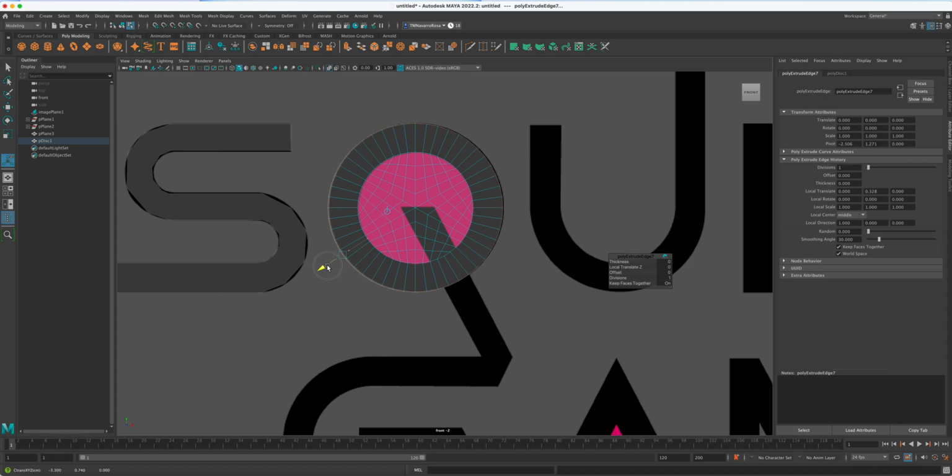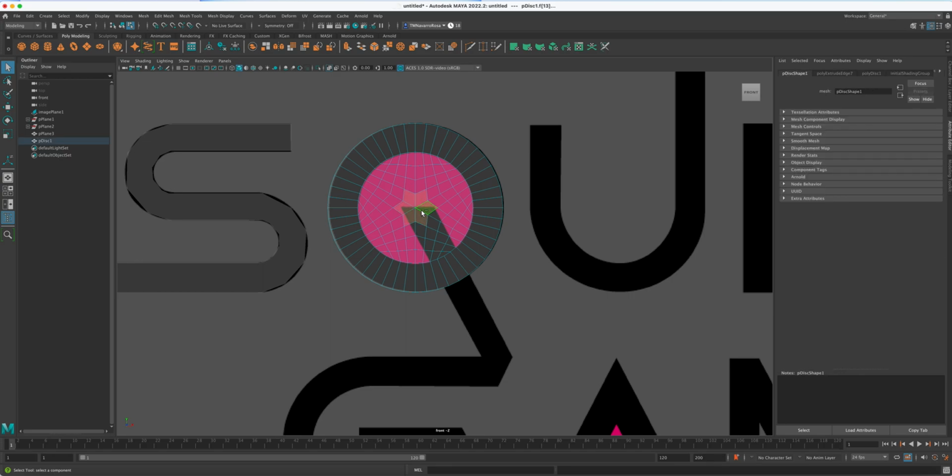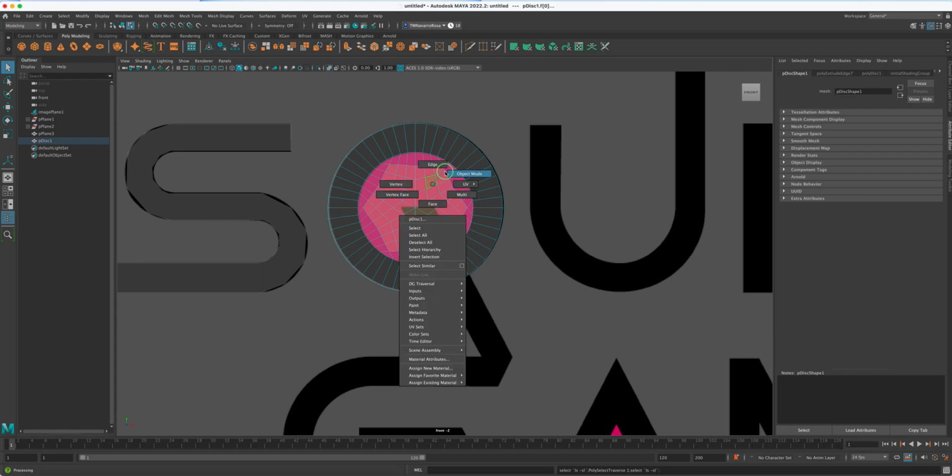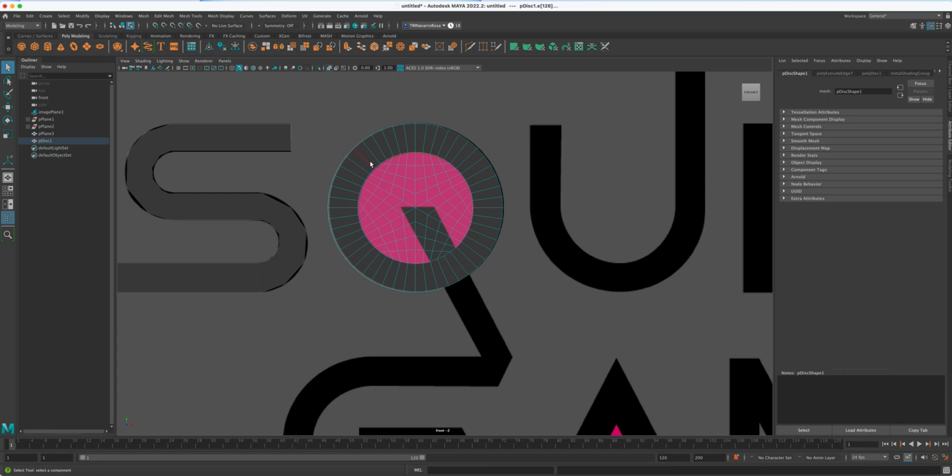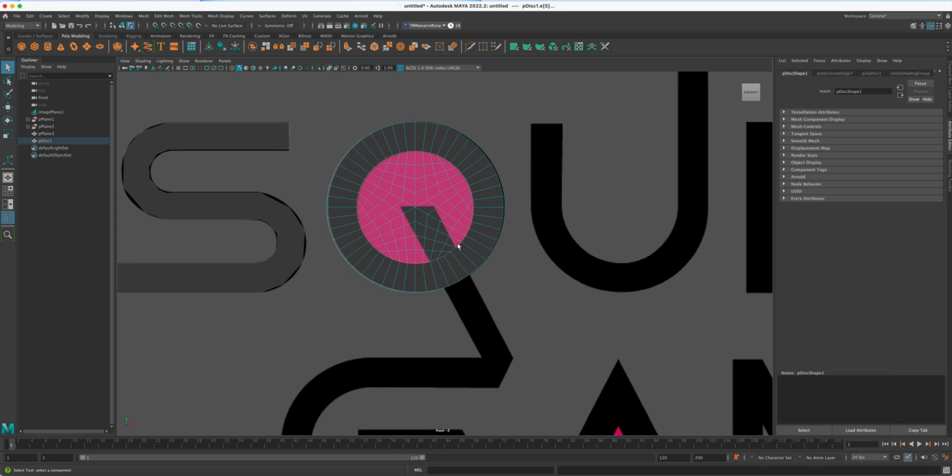Bam, simple. Now we're gonna select face, select only the 5 in the center, and when you press Shift and the period, you get this. The other way we can do it, if this is giving you a pain in the behind, is to go to edge, double click that edge, and keep going around until you select the whole edge, till it's all peach.